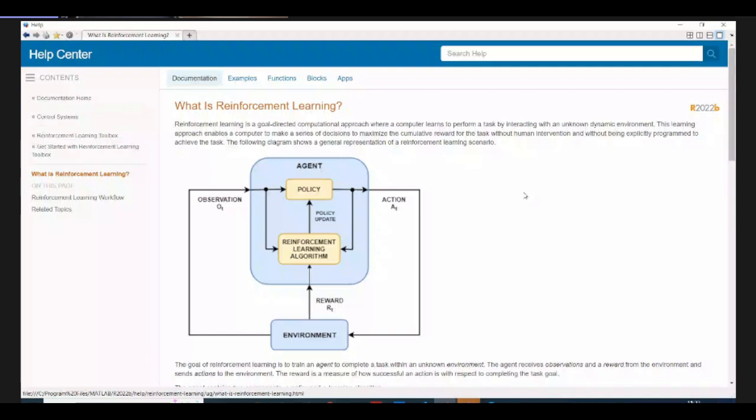Now, this is 2 degree of freedom. If I'm going to give the origin as my destination, will that be possible? Yes, it can be like this, and this one can be 180 degrees each way. Two arms are there. So elbow and shoulder, shoulder and elbow. Only elbow means only this movement. Sorry, only shoulder means only this movement. Elbow also have it, then we can have all this.